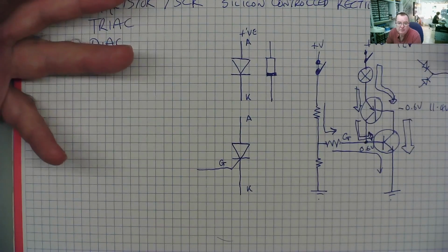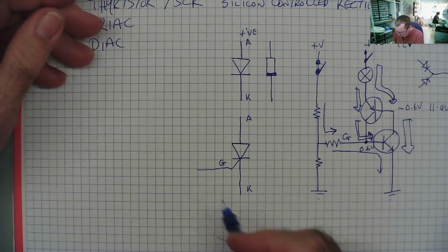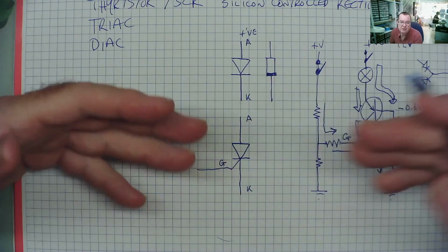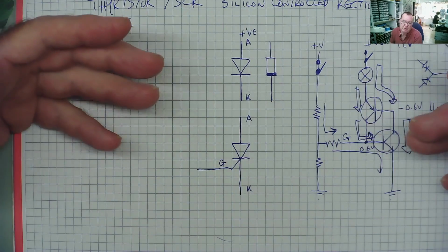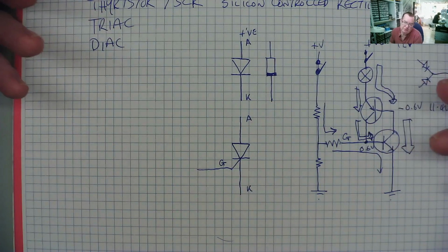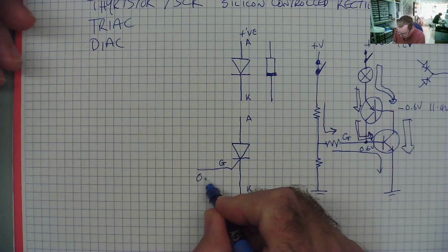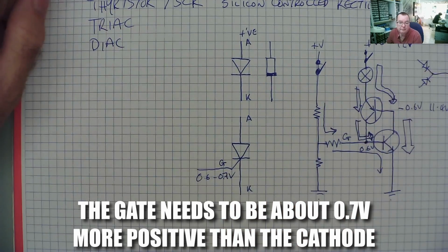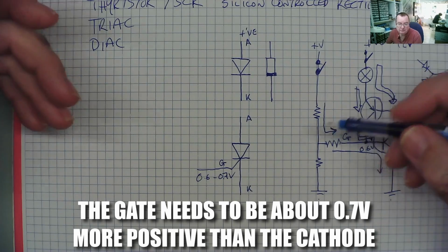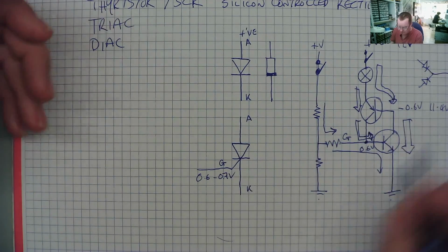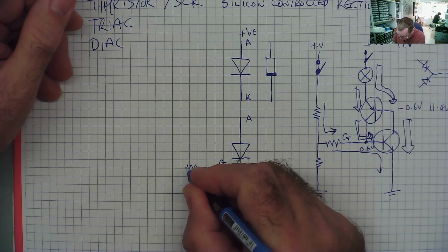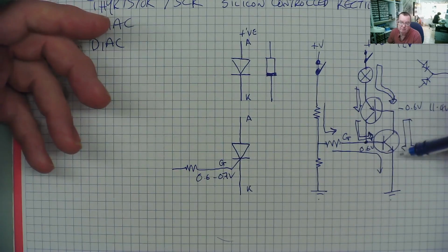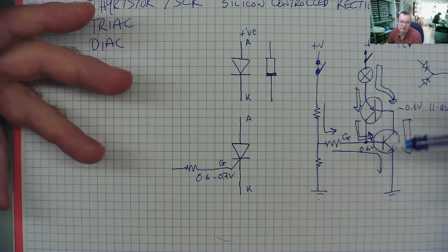From this then, we've learned a few important things. The gate voltage required to turn the thyristor on is roughly equivalent to the base-emitter voltage of a transistor, about 0.6, 0.7 volts. Okay? It's actually the current that switches it on, so we need to put a resistor in here to prevent an excessive current flowing and effectively destroying that junction. That's the second thing we've learned.